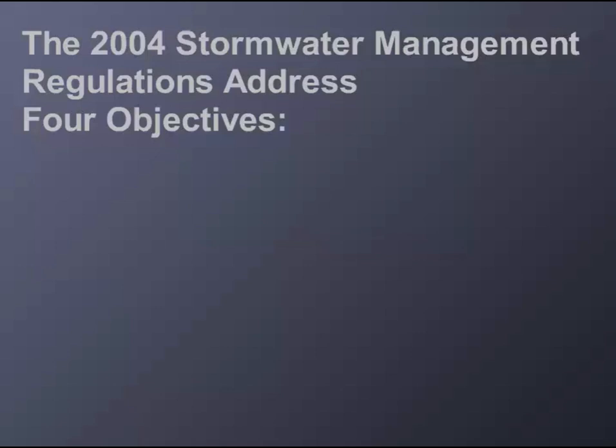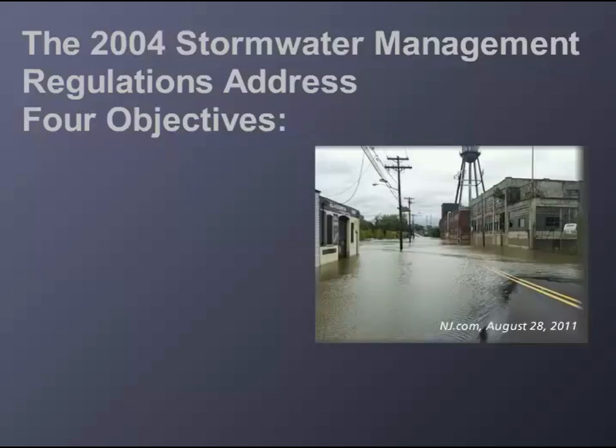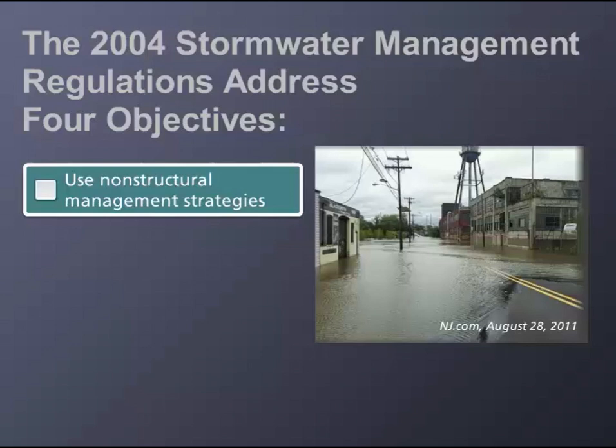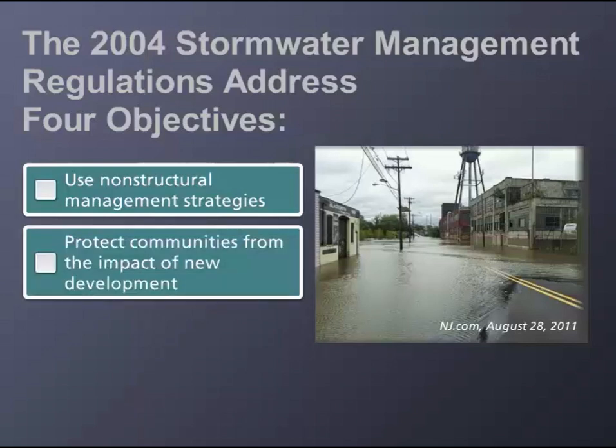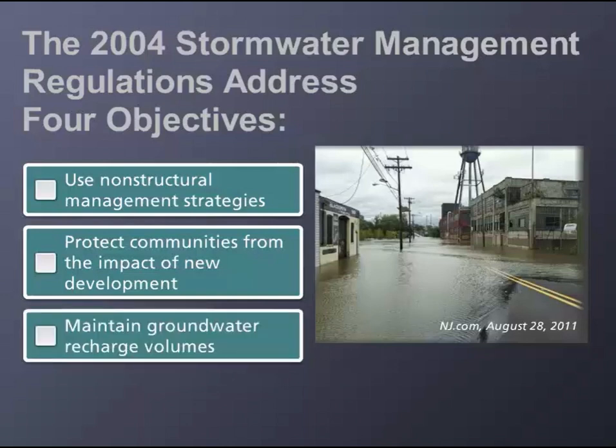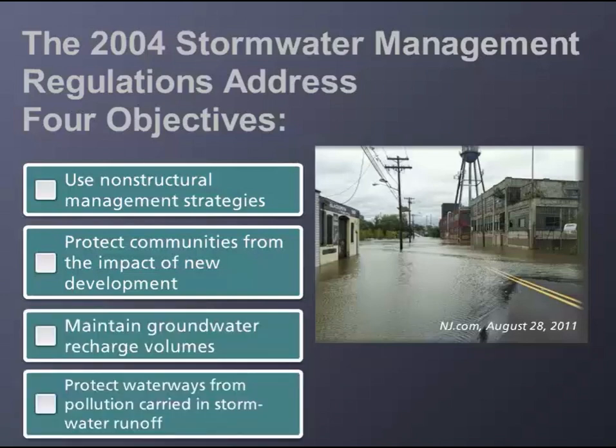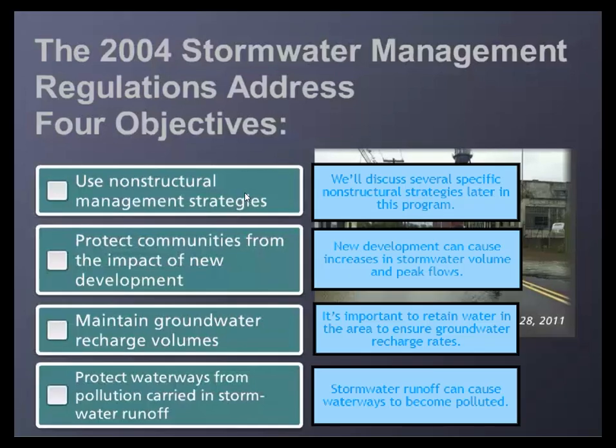The 2004 Stormwater Management Regulations address 4 objectives. Use non-structural management strategies. Protect communities from the impact of new development. Maintain groundwater recharge volumes. And protect waterways from pollution carried in stormwater runoff. Click on each topic to learn more. We'll discuss several specific non-structural strategies later in this program.